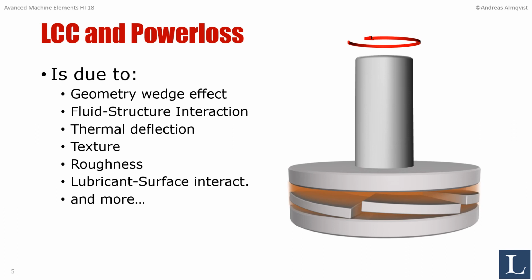There may be fluid structure interaction, and what I mean by this is mechanical deflection of the segments, the collar, and so on. This would be more apparent in the situation where you have a PTFE facing, which is quite a lot more compliant than the steel backing of the segment itself or the steel collar.